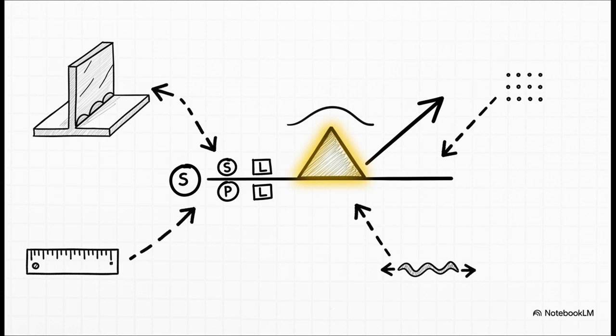First, that triangle tells us we need a fillet weld. Got it. It's sitting above the reference line, so that weld needs to go on the other side of the joint. The number to the left, S, that's our size. The numbers to the right, L and P, tell us the length and the pitch. And see that little curved line on top of the triangle? That's just an extra instruction telling the welder to finish the weld with a slightly rounded, convex surface.